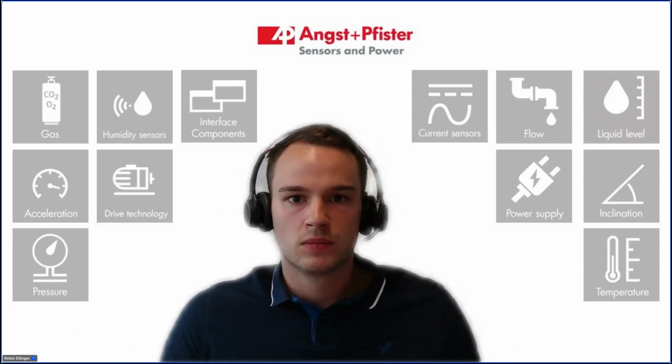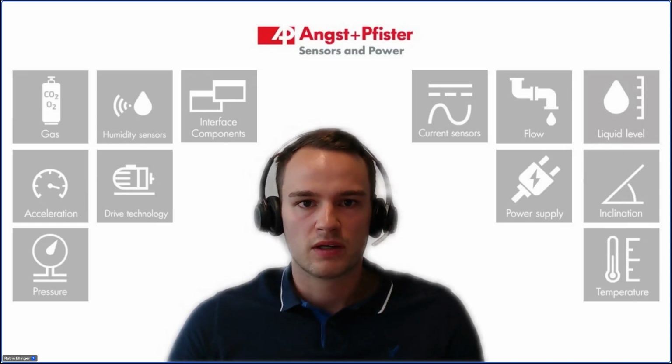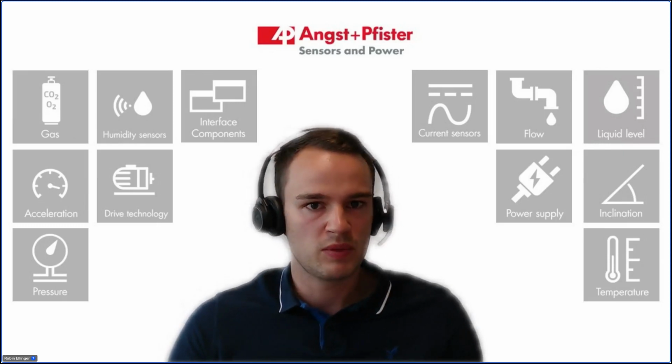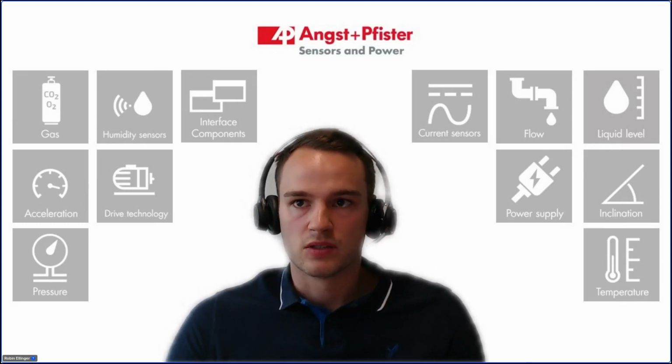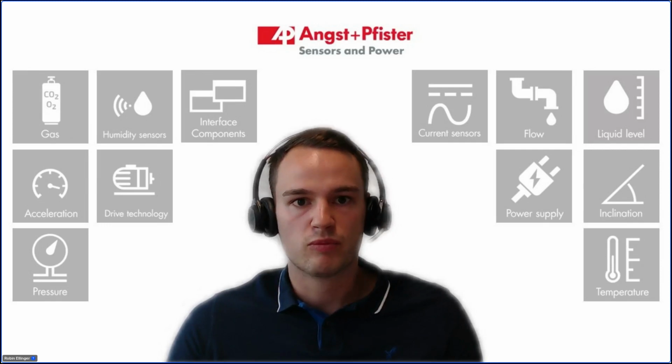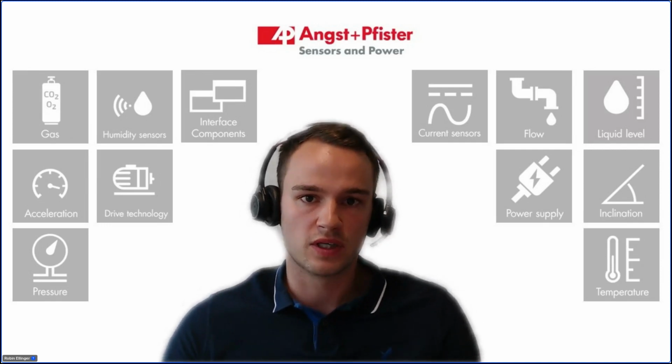Is there any restriction on the cable length for the SMT172? I wouldn't say so, to be fair. But in the past, we only sold the sensors with up to 10 meters of cable length, and it wasn't any problem. So if you want to have a sensor with more than 10 meters of cable length, we could still do some tests, but I personally don't see any problems there.